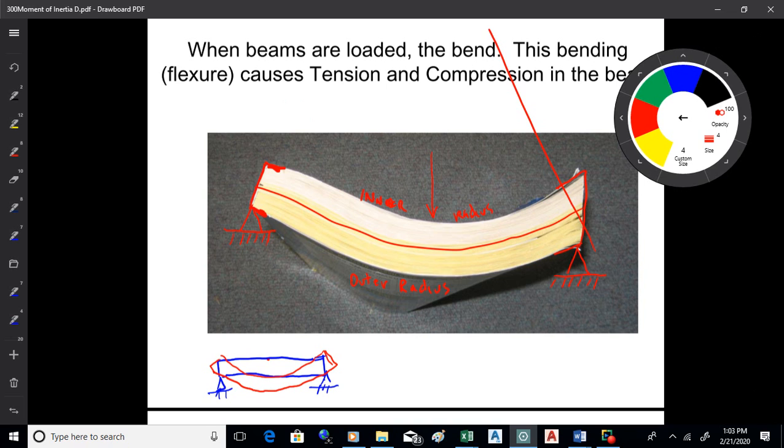So what the beam does is it holds itself together. And so that puts stress and strain on these atoms here. So this side has to get pushed in and this side has to pull out to hold that right angle, okay? So the bottom of the beam stretches and it's in tension, and the top of the beam, in this case, has to push in, and that's compression. Okay? So that's the deal. Right?